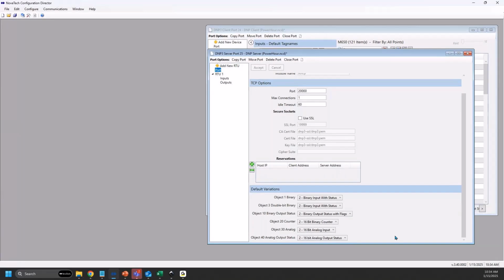It takes that decimal component and rounds to the nearest whole number. So if we set this up and sent it as a 16-bit analog, the value we would end up sending is 60, a whole number. Clearly that's not the precision we're looking for, right? Because the frequency is almost always around 60. Intuitively, we want a decimal component on hertz.